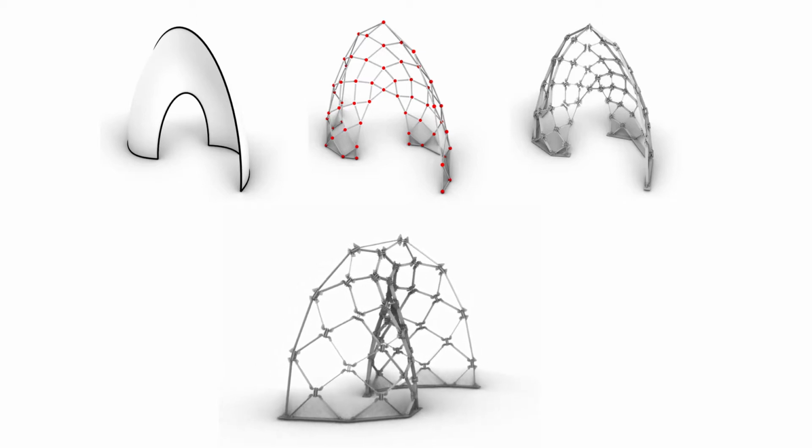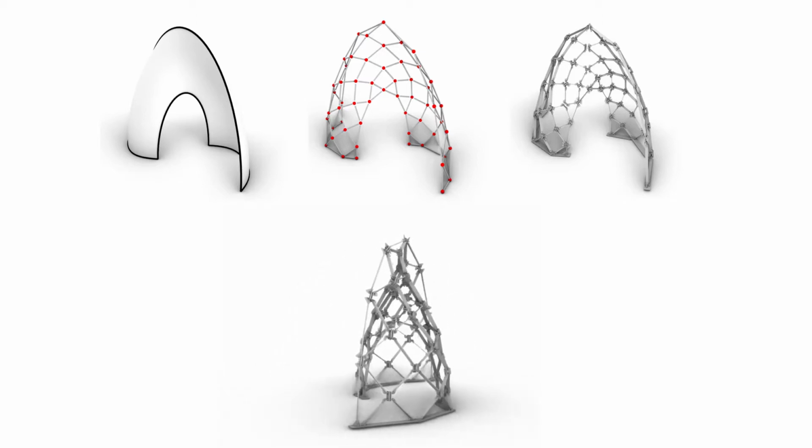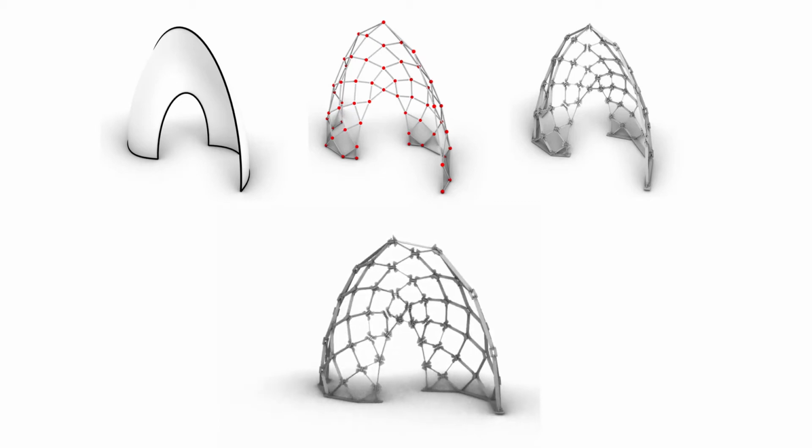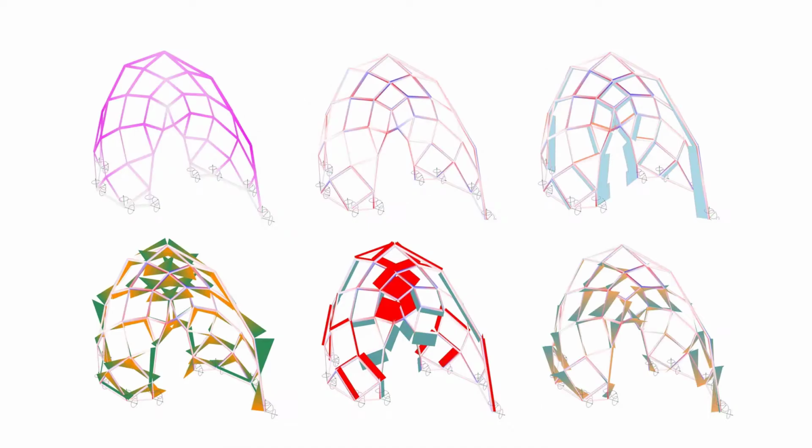Nodes undergo different axial stresses, and therefore the integration of the nodes is examined under tensile, compressive, and shear forces. We analyze the structure via Karamba 3D plugin, which uses the finite elements method in the Grasshopper environment. You can see the utilization of the structure, which means the amount of stress the entire structure and each bar bear compared to their capacity, in the first two figures. The longitudinal shear forces and the axial stresses are depicted in the rest of the diagrams.